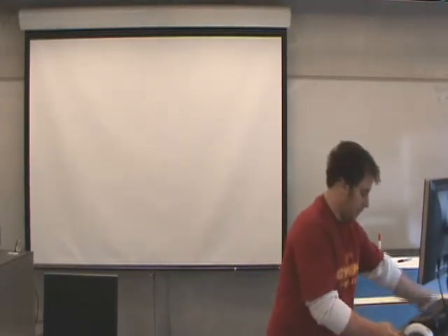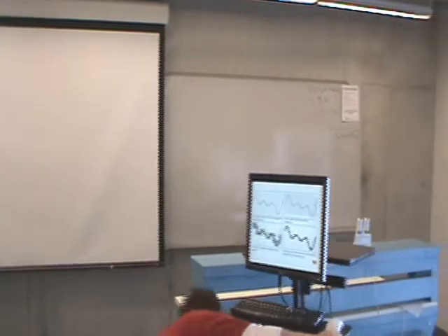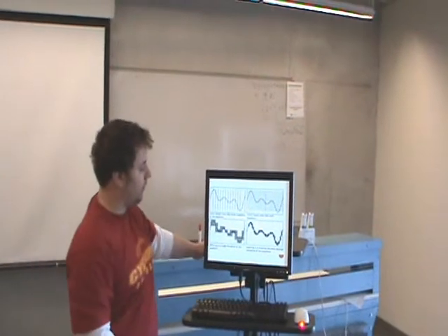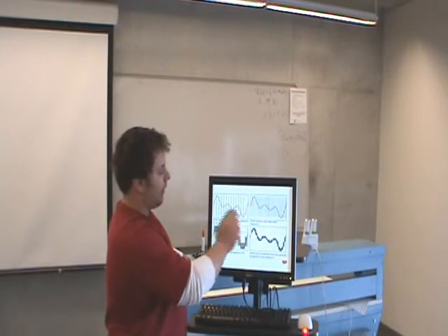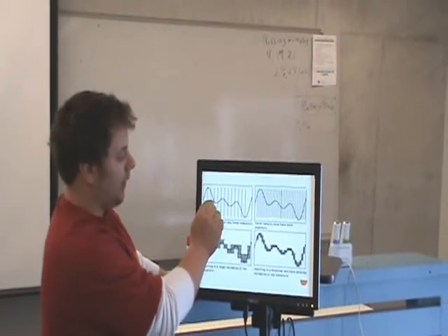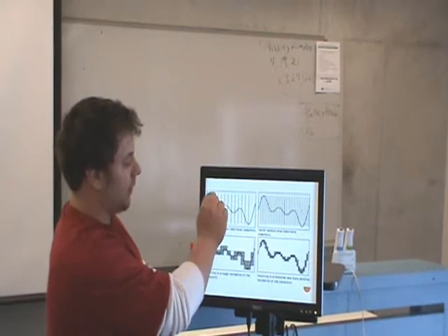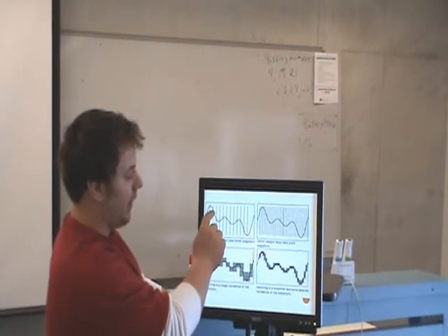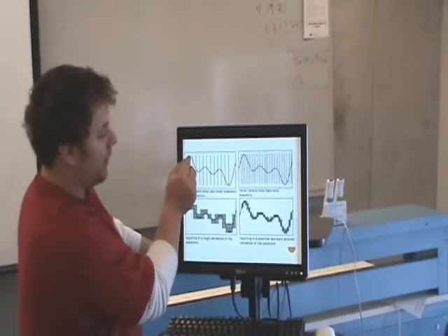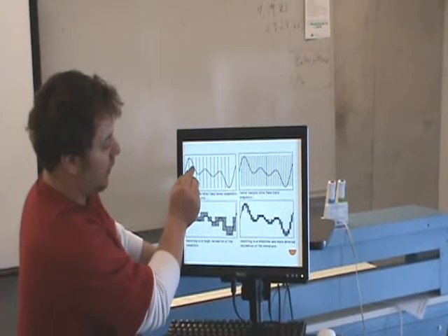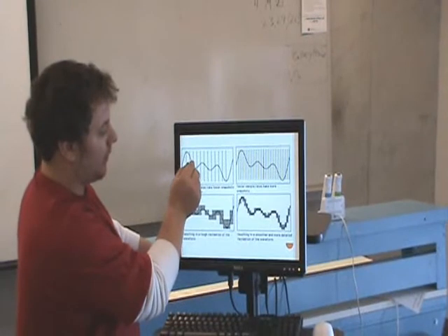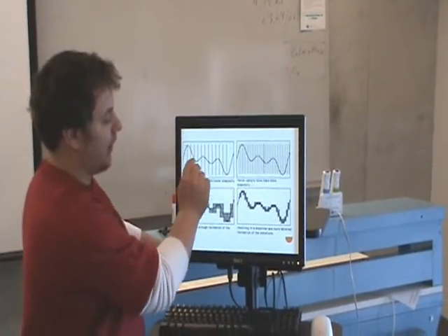Here I'll turn this so you can get it close up. This is a little bit what the sample rate can do for you. You see this bar graph here. If you only take samples at the particular lines, your end result's going to look like a square wave from this line down to here. And obviously that's not what this particular wave looks like. So if you sampled halfway in between, it would look more like a diagonal line rather than a square wave, and every time you make more samples, just like the pie, you get closer to the actual signal.